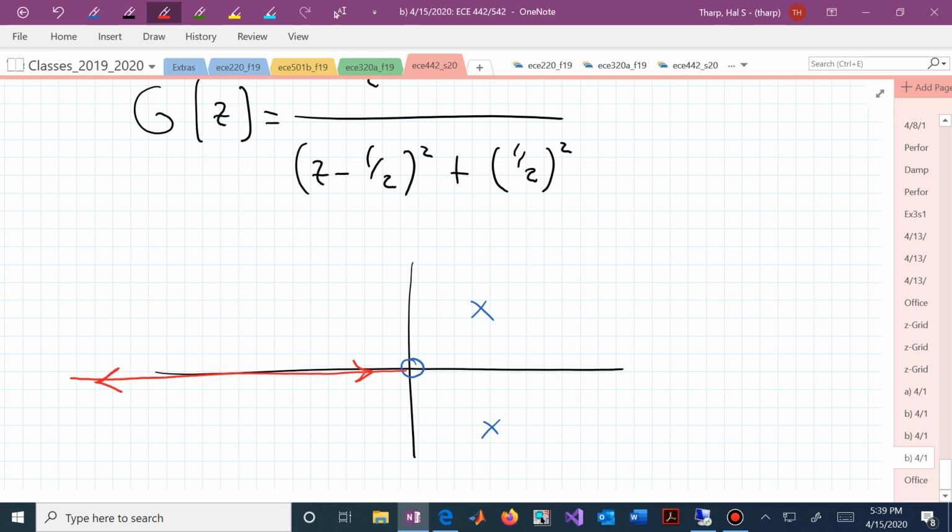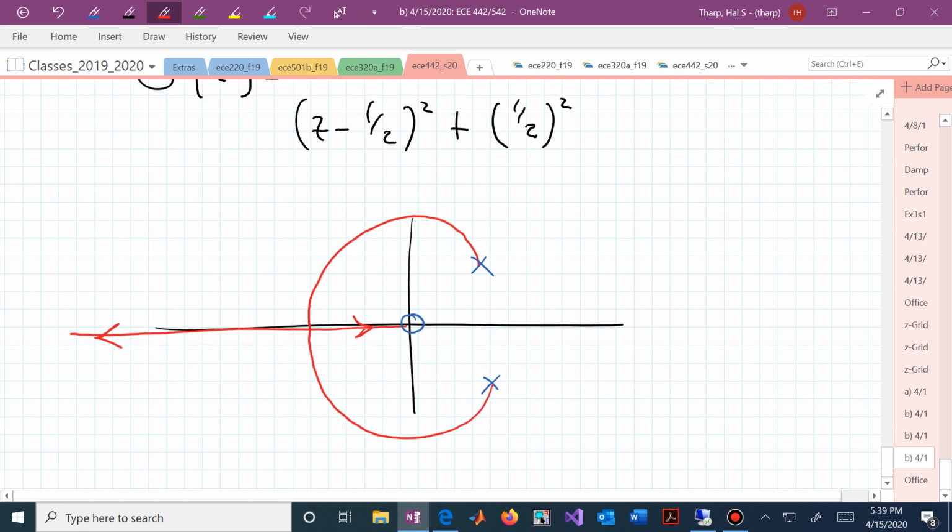We start on the poles, so now how do we depart from the poles with our root locus? Do we go like this? And in fact, this is sort of this 2 poles to the right of 1 zero structure.